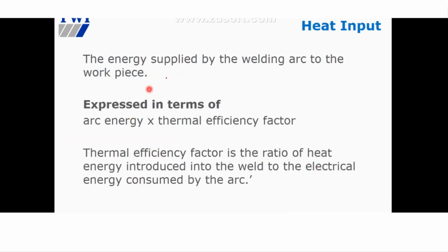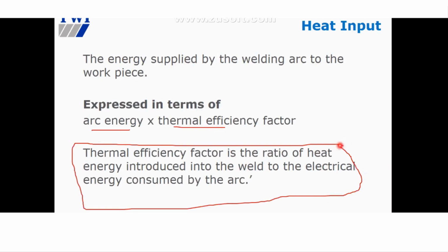The energy supplied by the welding arc to the workpiece is expressed in terms of arc energy times thermal efficiency factor. All right, so memorize this one. What is thermal efficiency factor? Maybe they ask you about this. Memorize, highlight this. Thermal efficiency factor is the ratio of the heat energy introduced into the weld to the electrical energy consumed by the arc.